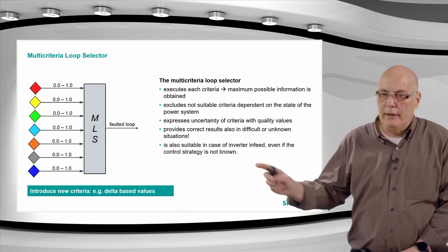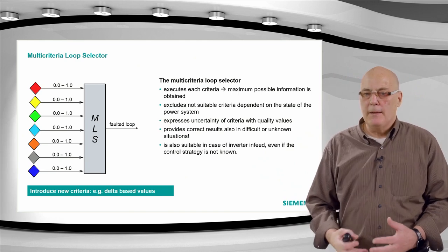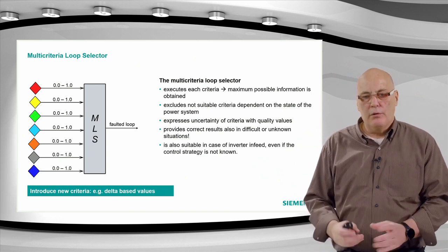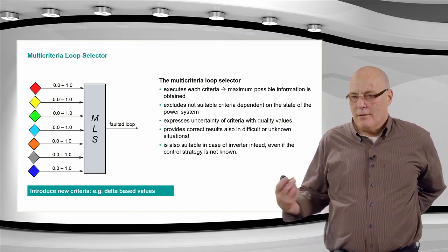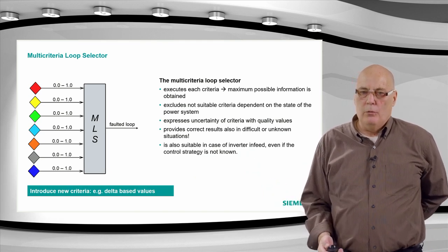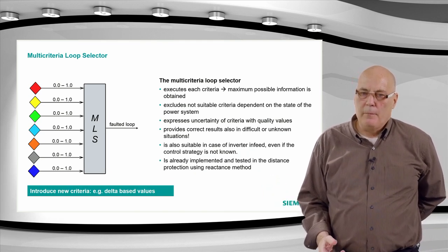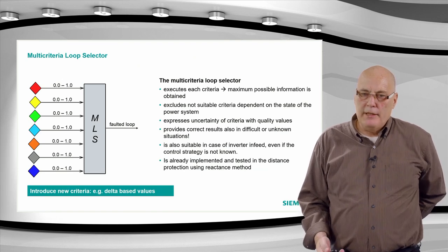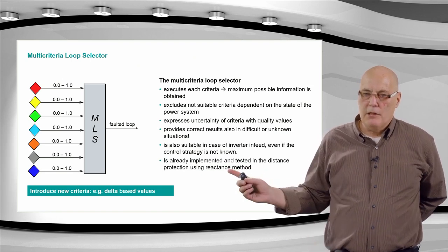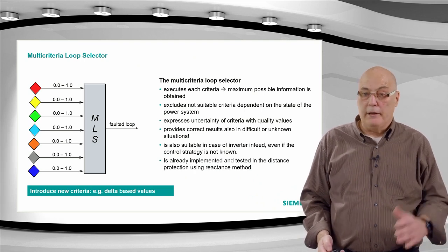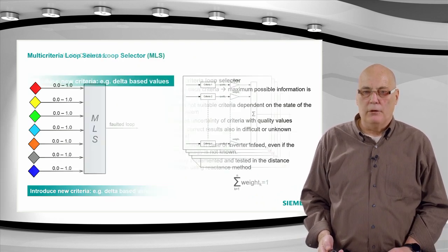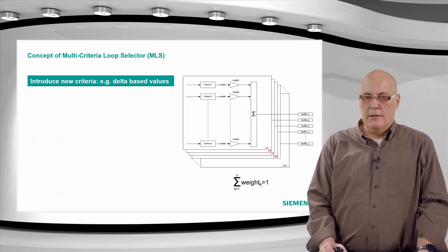And important here, it is also suitable for inverter infeeds if we know the control strategy to a certain extent, and that we do know. Because the fault ride-through techniques are now defined, and we can deal with those inverter infeeds. It's already implemented, tested, and it's running in the distance protection with the RMD technique. It has been using this for a long time now. From the beginning of the RMD, essentially, it's been using this. It's not new in that sense.